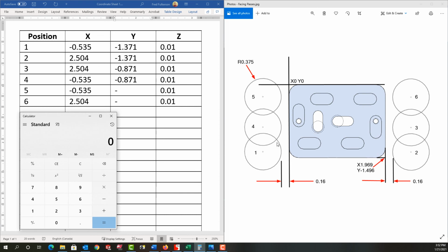Since I've taken a 1/2 inch of material this way and a 1/2 inch material when I came back, there's only the 1/2 inch of material left. So what I would like to do is put the cutter center so it overlaps this cut a bit. If I only move it down 1/8 of an inch, this edge will be right here. So I'm going to program for 5 and 6 negative 1/4 inch, and then I have a bit of overlap here and I have overlap here.